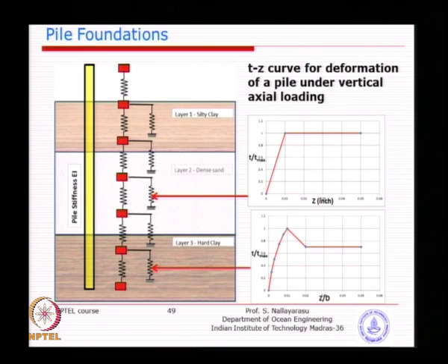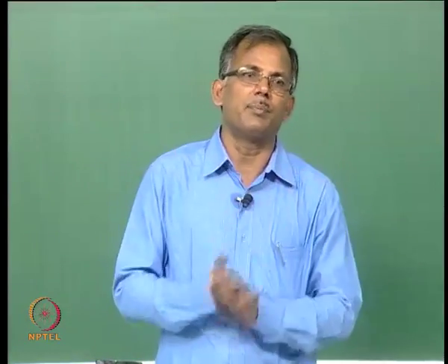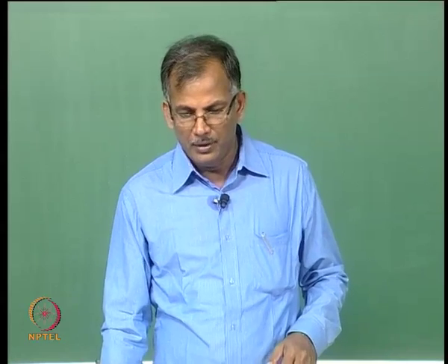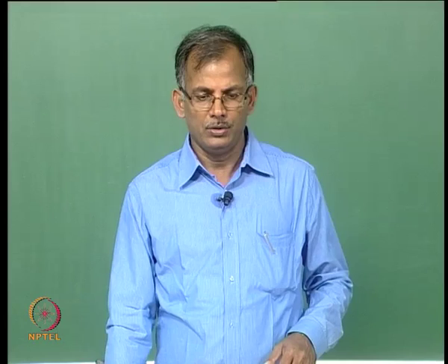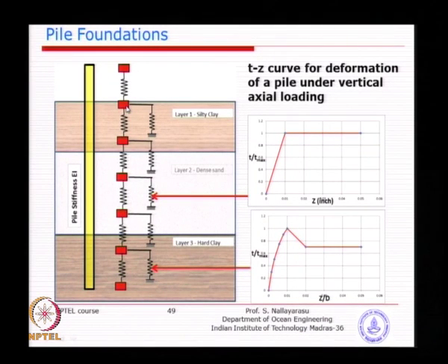So, that is how most of the offshore structures are characterized. You have a structure, you have soil as an engineering material, you transfer the strength properties in terms of springs and then you analyze. So, this becomes part of the structural system. You divide the structure into various subcomponents, each component is attached to the next one. For example, this element is attached to the previous and the next, and also attached to the side soil with a certain spring. Once you establish this, then you can carry out the analysis.